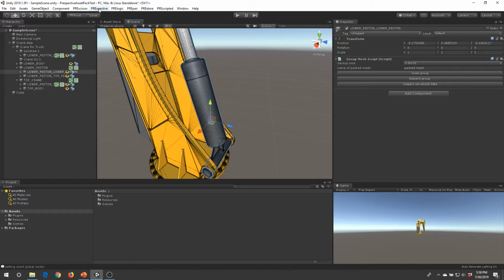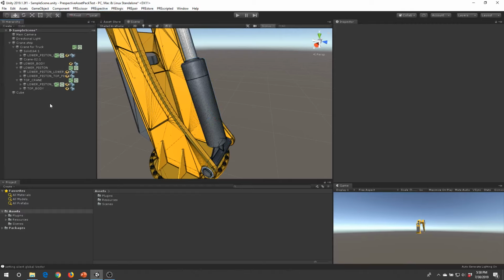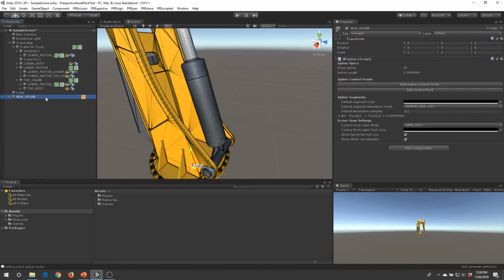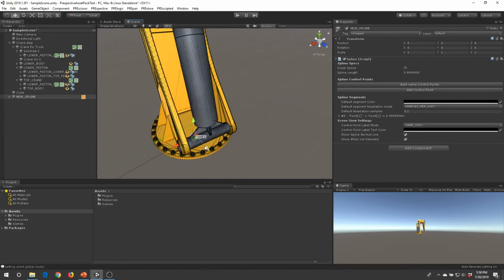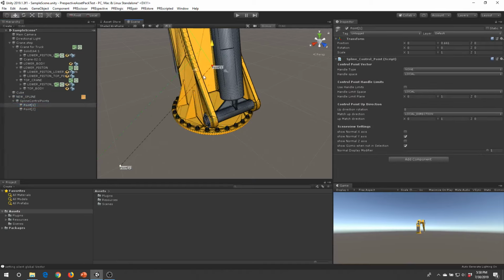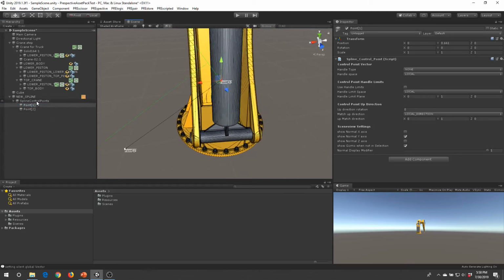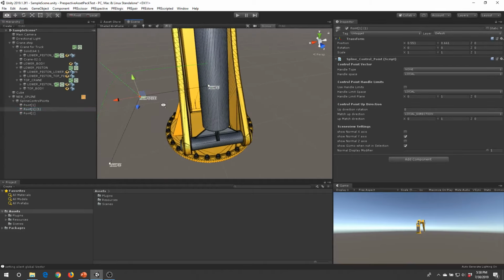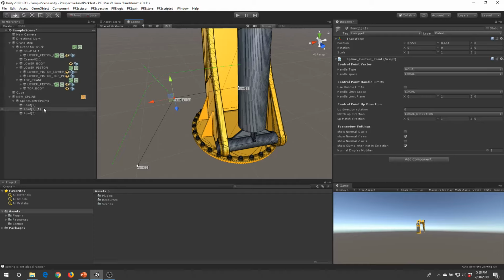So to add a spline, we'll just say Perspective, Spline, and Create Spline. And that'll just create a new spline down here, and it's always just 2 points positioned at the origin and 1 meter. We can move the points around by just selecting them, and this will also change the line. If we want, you can create a very complex spline by just adding in different points. Let's show that now. So now we just inserted a point and copied it back into the center.